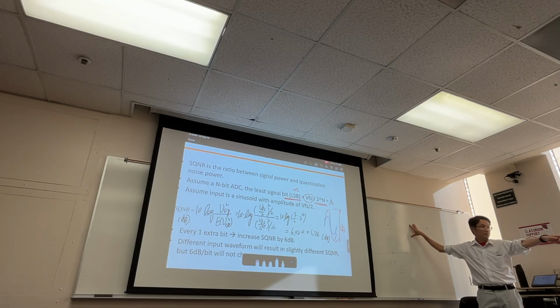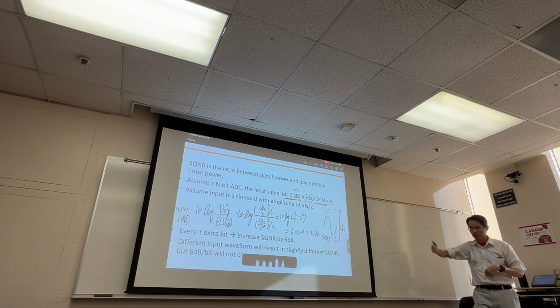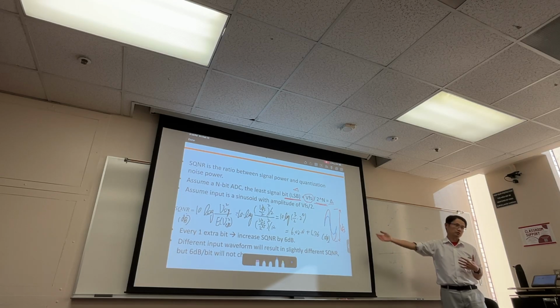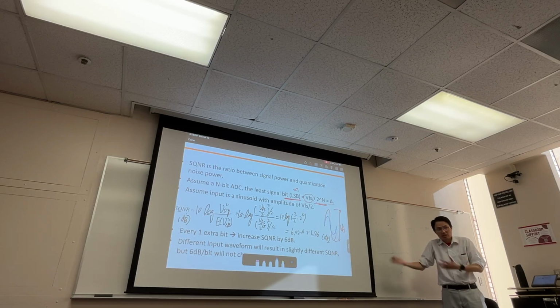And also remember we talk about aliasing, right? How do we take care of the aliasing? The filter, right? So yeah, if you can get an ADC super duper, like sampling super fast, high speed, you can also relax the filter a lot. So I feel that the whole world that we are learning pre this class, anything that you learn, it's just because we don't have a good ADC. So we need something else to help the ADC guy. Yeah, the ADC guys need to work harder, right? That means that you guys need to work harder, right?